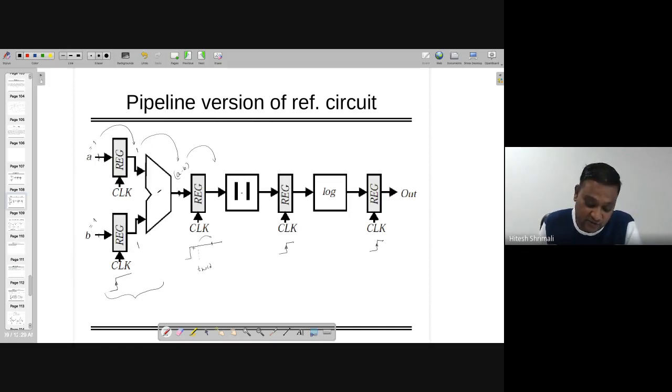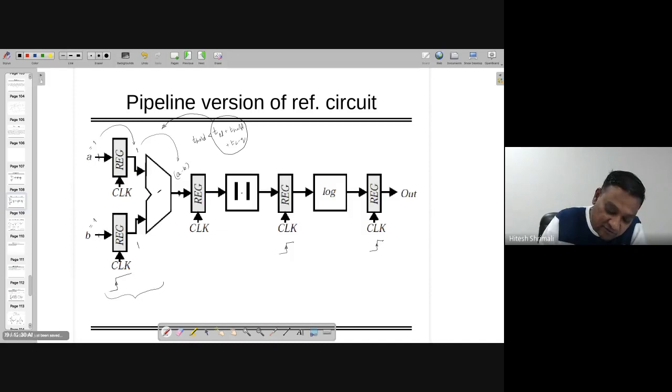But if you are making the hold time of this register somewhere here, then this data will go that side, right? Because there is a transition from 0 to 1. So we have to make sure of that, otherwise this thing will be problematic. So the hold time of this register should be much lesser than the propagation delay plus the contamination delay, all these things of the combination of both the register as well as the ALU.